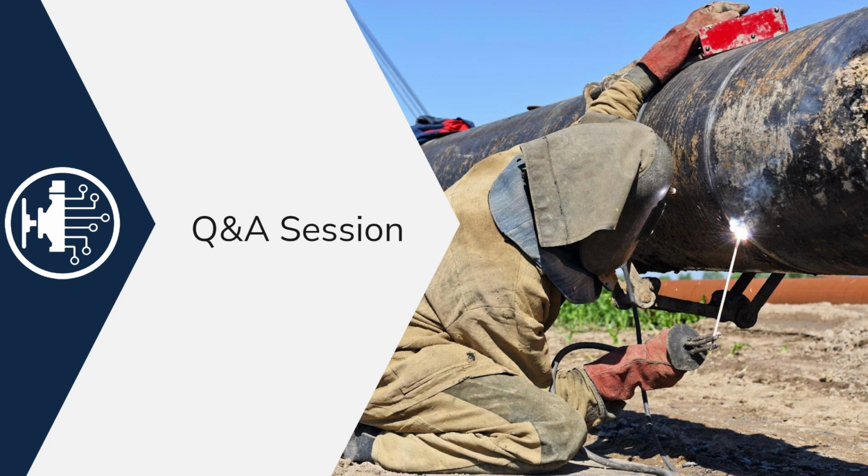Now, that repair is a coating, sleeve, whatever it may be, simulating pristine pipe in that area so you can safely operate your pipe at that desired MAOP. So what does this do? No matter how long your corrosion length is, this provides engineers a tool to run their analysis effectively and reliably in a very quick manner.